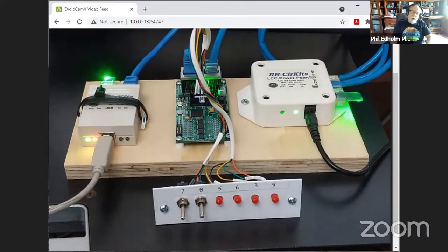We have Cat5s running. So if you have a signal remotely, basically the signal base has 2 RJ14s to go to the signal tower. It's got a Cat5 plug that you plug in to run back to the panel. And all the wiring is going to be star-based Cat5 wiring with the intelligence very centralized, because it makes it a lot easier to manage all the maintenance down the road. Because if I can sit at one point, I can look at the wires, and if I know that wire's got positive, I know it's positive at the light that's 15 feet away or 30 feet away. So I think it'd just be a really interesting debate.